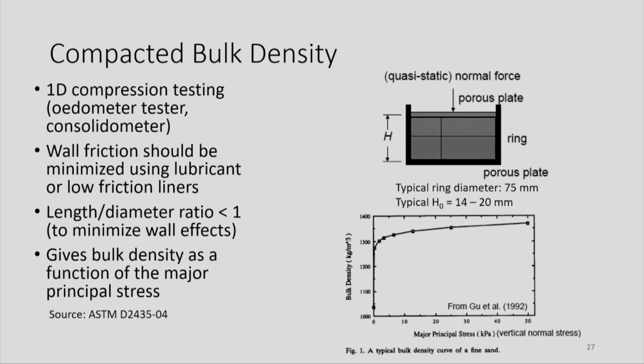But let's say another subject, like aeration. You said aeration, right? It's highly related to aeration of grain bins. Okay. So again, compacted bulk density. How do we calculate it? By uniaxial compression, one-dimensional compression. So you put samples in a container and then just compact in one direction. Okay, you control the forces on all the other three sides and just apply force from the top.